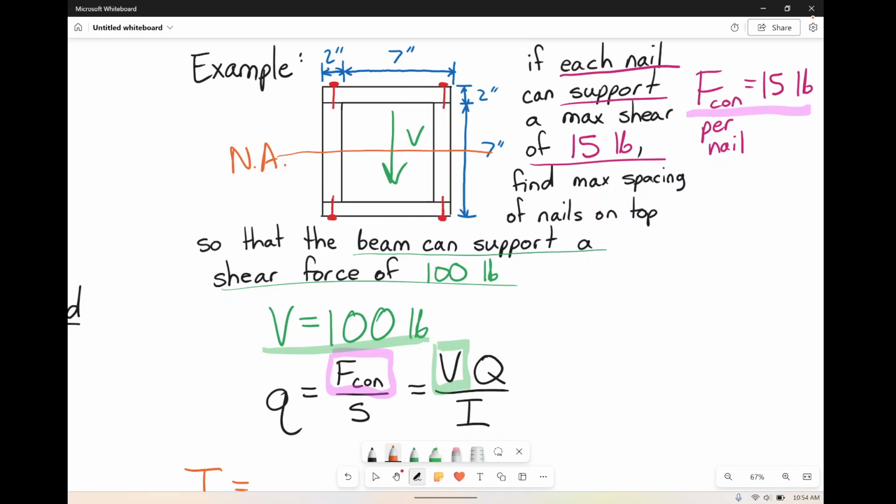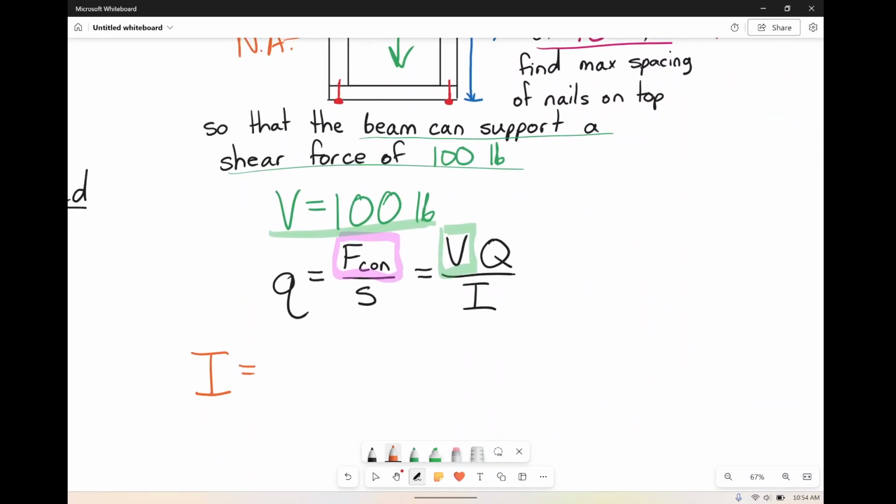So technically you might be thinking, oh my gosh, I have 1, 2, 3, 4 rectangles. This is going to be a really long equation, but let me remind you of something that's really cool when it comes to moment of inertia, that you can add and subtract shapes. So how I'm going to solve for this is I'm going to look at it as though I have my really big square, and then I'm going to minus out the small square.